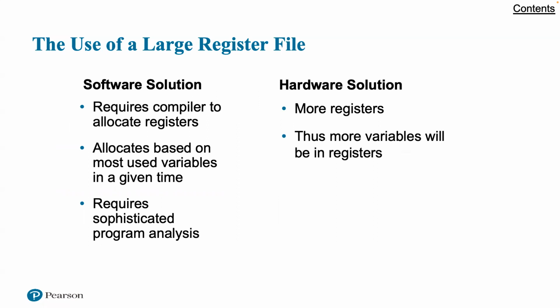The reason that register storage is indicated is that it is the fastest available storage device, faster than both main memory and the cache system. The register file is physically small, on the same chip as the arithmetic logic unit and control unit, and employs much shorter addresses than addresses for cache and memory. Thus, a strategy is needed that will allow the most frequently accessed operands to be kept in registers and to minimize register memory operations.